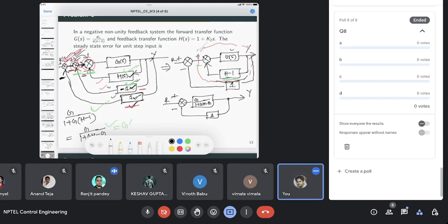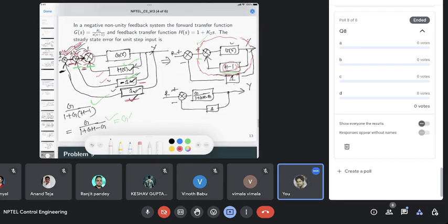This red one, I can simplify that, right? I have G(s) and this H(s) value is this H minus 1. I can simplify the feedback formula and apply it for the inside loop. So this is what we get by combining them, right?